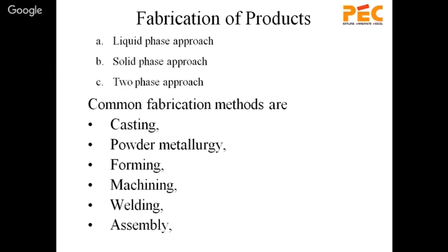We go for it this way: first, aluminum is put into a ladle and the ladle is placed inside the furnace. Say the capacity is 1000 degrees centigrade, and we allow 2 hours, maintaining the temperature at 710 plus or minus 10 degrees, so that it melts. Then another furnace is used simultaneously, where we put another ladle of alumina or silicon carbide or both together.